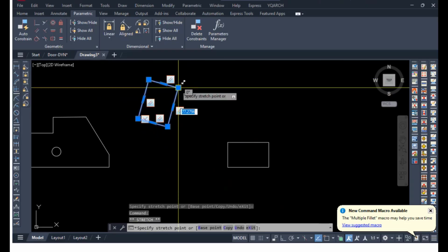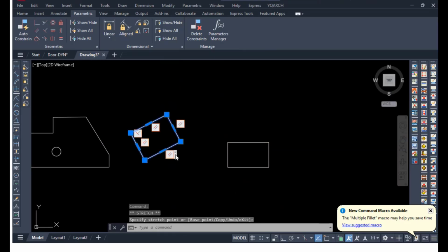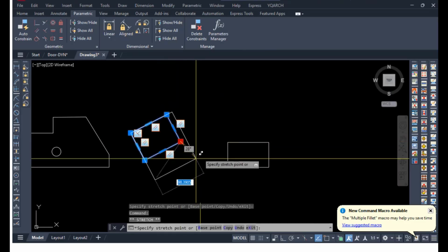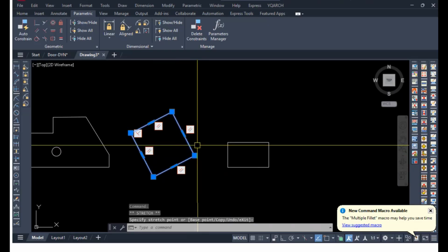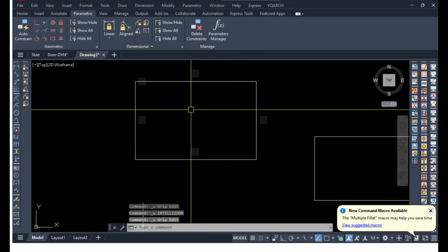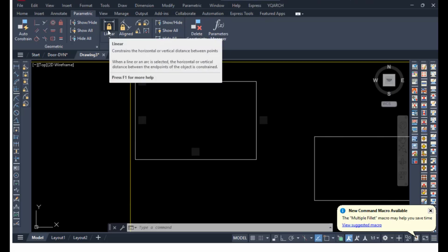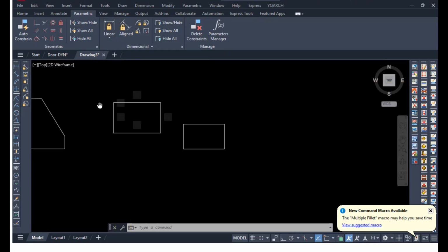You see, this is a benefit of constraint that lines alone can't do at all. However, if you want to adjust this rectangle to be a square, it's easy. Normally, we apply the equal constraint. A square means the horizontal and vertical are equal, right?